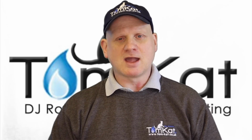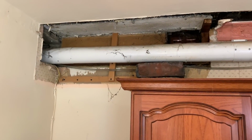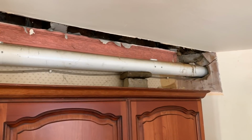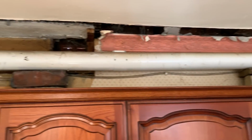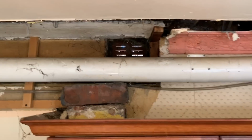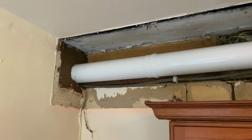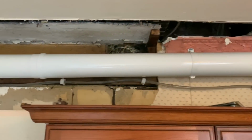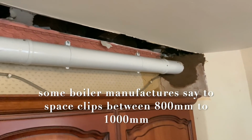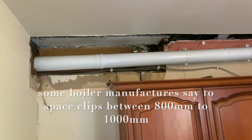Anyway, let's look at how we're going to clip this flue system. Now, is the engineer who installed this flue system a genius or an absolute balloon? Because they used bricks instead of clips to hold the flue up. So unsecured flue using bricks, at risk. So we replaced the boiler and the flue system, and we used the correct clips with the correct spacings, so clips should not be more than 1.8 meters apart or every change of direction.